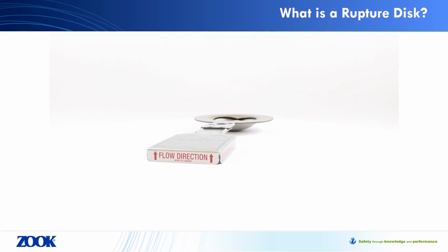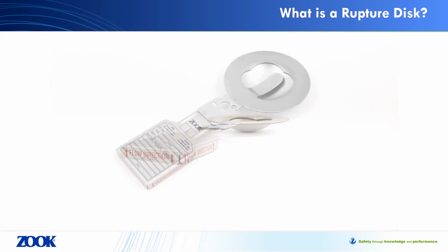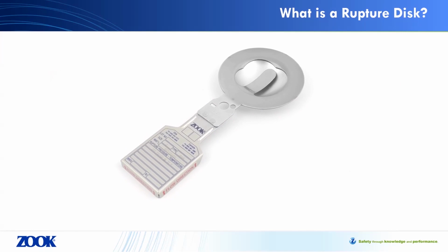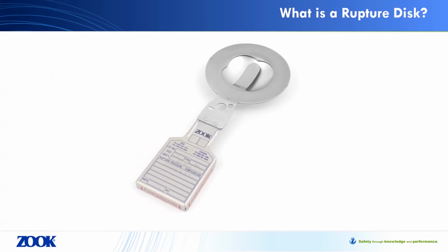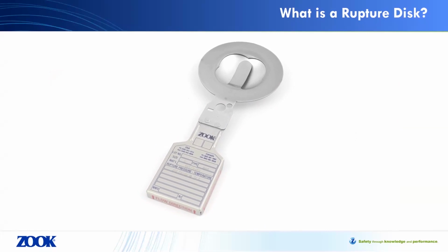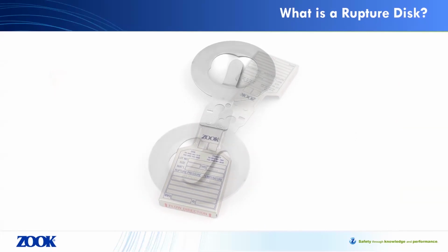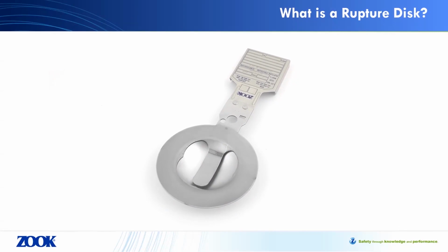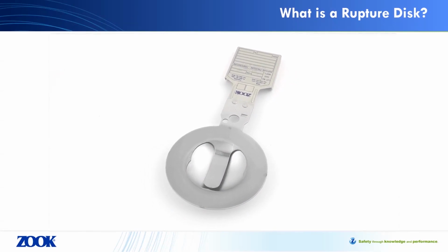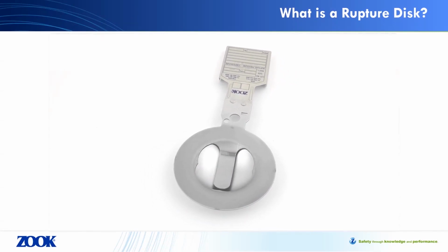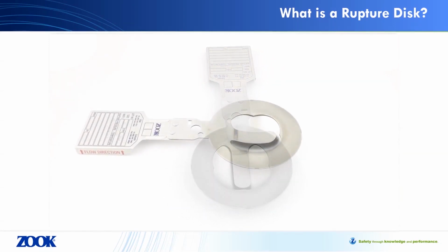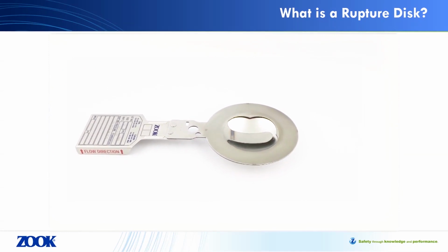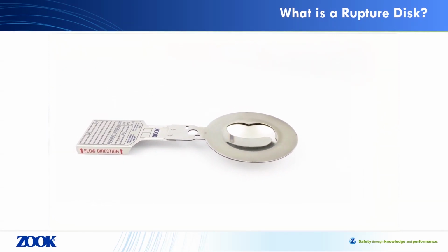One of the differences that I'll bring up now is that a rupture disc is a one-time use device. All rupture discs use a thin diaphragm piece of material engineered to specifically rupture or fail at a specified pressure and temperature. This diaphragm material is traditionally composed of various types of metallic or graphite material. For the purpose of this webinar, we will be discussing metal rupture discs specifically.